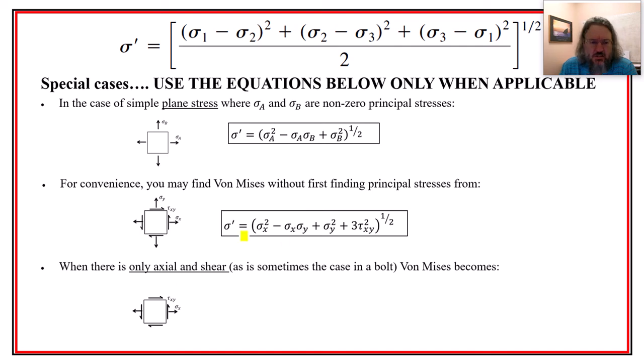It's hard to get stress in that other direction, like right up here. It's only in that pressure vessel we were able to get it, and that's because the hoop stress goes in the opposite direction, right? All the other stresses kind of align with each other. The bending and the axial and the longitudinal all go in the same direction, but it's only the hoop that goes perpendicular to it.